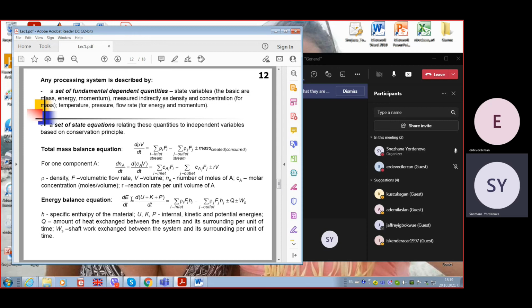So this balance equation is related with the heat that comes with the inflow, this mass of inflow, minus the heat that leaves with the leaving liquid, the external input or loss through ambient influence. For instance, ambient temperature is very low and we lose energy. So this is the relationship with environment.